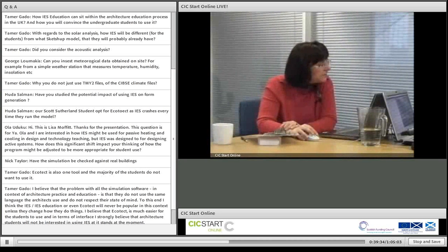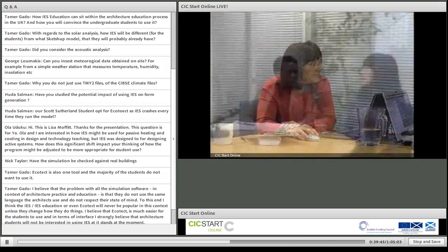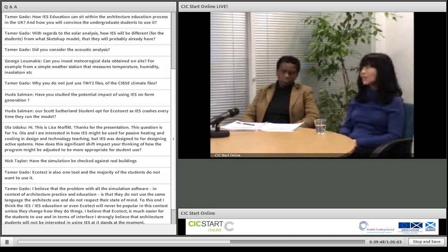Another question from Tamer. Why do you not just use TMY2 files or the CIBSE climate files? I think that is an option, isn't it? Yes, we have the CIBSE weather files as well, TRY and the DSY, the test reference year data and the design summer year data as well. It's definitely yes. In IES VE weather data, we have different types of weather files. It's a total user option. That's correct. Whichever data is suitable for you, in your case study, you can choose it.